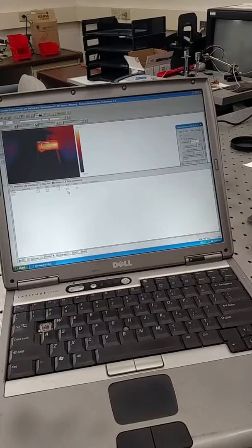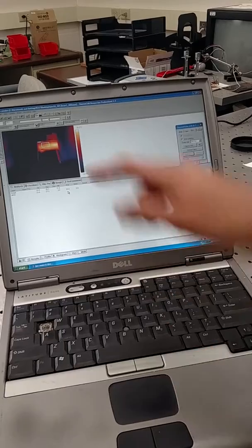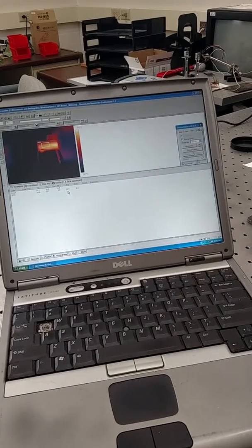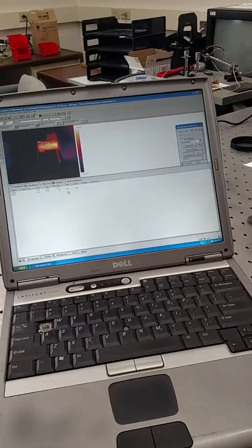Also, because these metal things are touching, I feel like the metal's getting a little hot too now. See, the metal's starting to show. The reason it's starting to show is because it's getting hotter and getting in that range. The reason it's also cooling down is because it's touching something. The metal pieces are acting as heat sinks. Therefore, it's able to cool much better than our samples, which are just in free air. Okay.